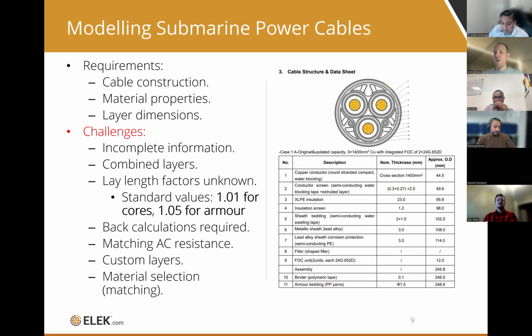Now, we don't know how they've performed the calculations, whether they're doing fully compliant IEC calculations. They're certainly not measuring it. They're using software, either our software or something similar, to calculate the rating. It's a good idea once you've modeled the cable to do a sanity check calculation and just check that you're in the ballpark, because these calculations are very sensitive. If you get a material type wrong, if you get a thickness wrong, it can very much affect the current rating. So we've got to make sure that the model is correct.